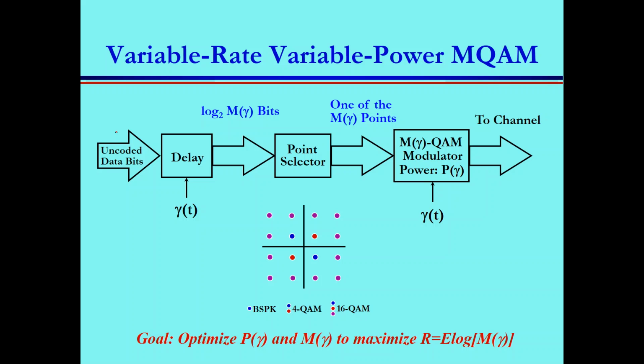And then there is the receiver. If the transmitter is going to use adaptive modulation, he needs to be in a waiting process here, waiting for an update from the channel. Yes? Why? Here, the transmitter suffers from some delay. He needs to wait for the receiver to send him something so that he can adapt. Can he adapt blindly? He cannot. He needs to get some information about the channel, the application. And to get this information, you must be patient. That's why it delays your transmission a little bit, because you need to get feedback. I wait to receive feedback and accordingly I adapt.